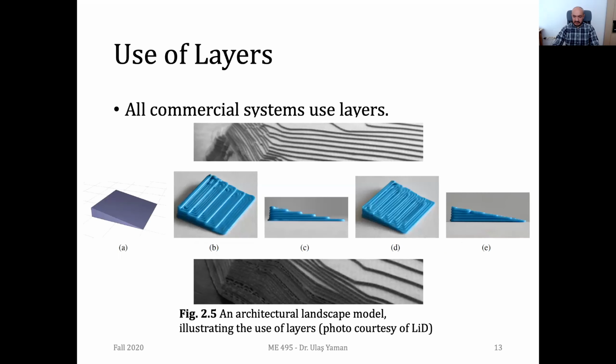But here you see, we have an example, a nice implementation. I think this came out around 2017 or 2018. What they did, this is a conventional FDM printer, a fixed line fabrication system. If you follow the conventional design and fabrication, you'll have such a staircase effect on this almost horizontal surface, which is a very low, shallow angle. You can easily see these stairs. But once you apply an improved approach, this will be the result.